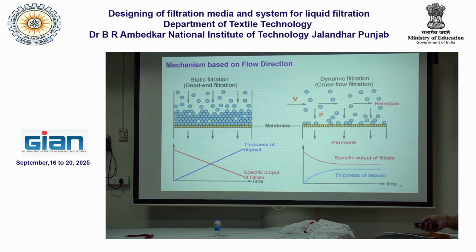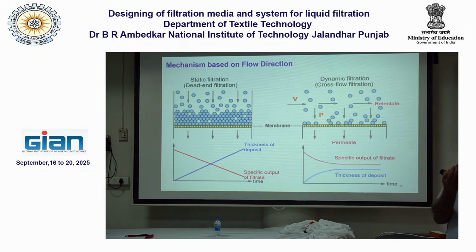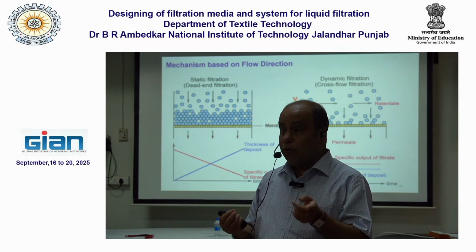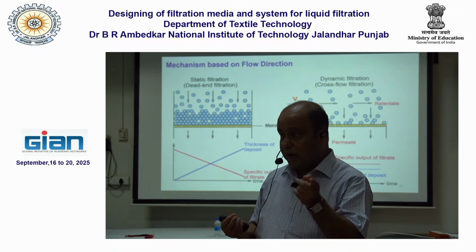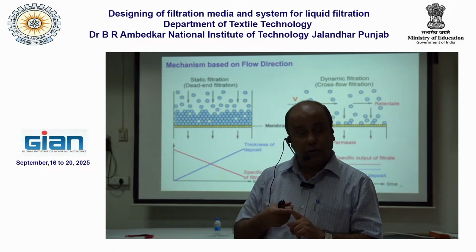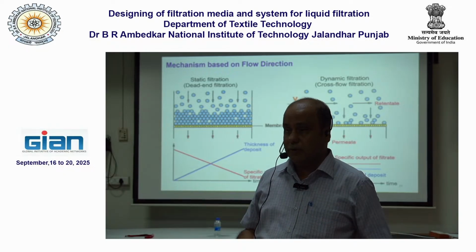And sir, if you compare the flow rate of dynamic filter media and static filter media, which one has a higher flow rate? No, that all depends on the requirement. See, what contaminants you want to remove. As I told you in my earlier class also, if you make the material very compact, okay, obviously you can remove very small size particles, but throughput will get affected. Okay, pressure differential will be more, throughput will get affected. Okay, so it depends on the requirement. Requirement is different from place to place.